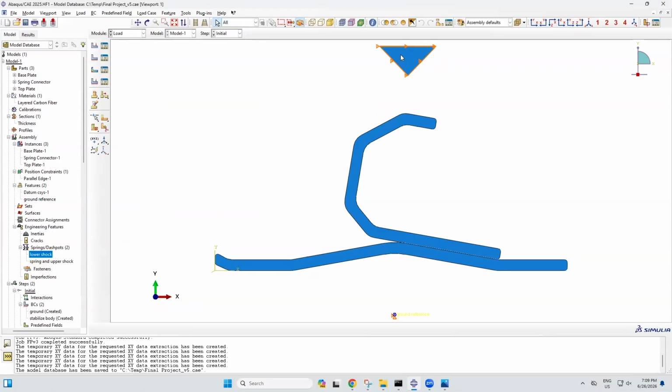Because I made the spring connector rigid, it does not matter where I applied the load on the spring connector, because it is only allowed to move down. Thus, any weight or load applied will automatically force the overall part to move down.